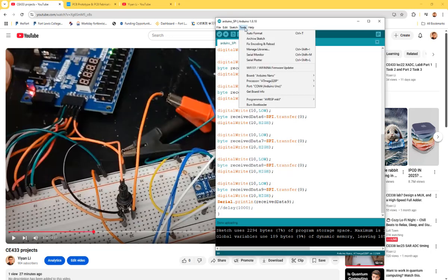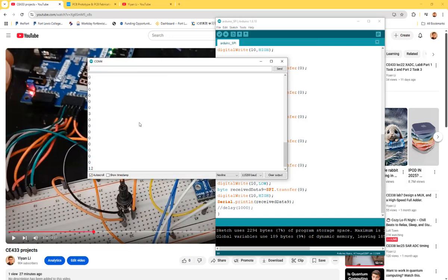So the plotter is not doing a good job. The serial monitor is doing an okay job. You can see most of them are zeros. So how do we do the data processing? And I believe if you change the data to like maybe 100 or 50, it's gonna be like a bunch of 50s and have a little error message in the middle getting plugged into it. So definitely these data points can be filtered out by a low pass filter. But what else can we do, right?